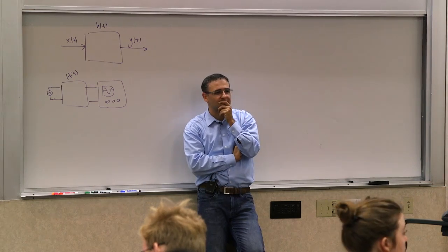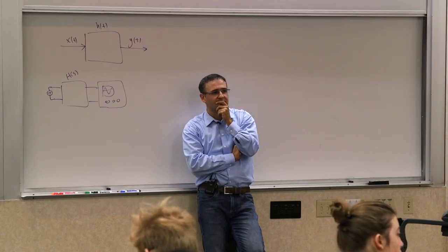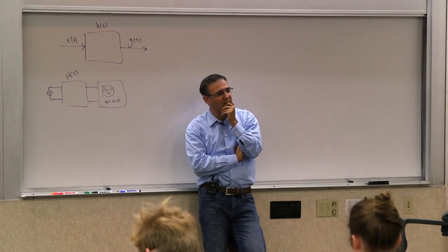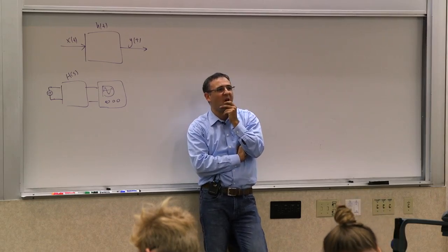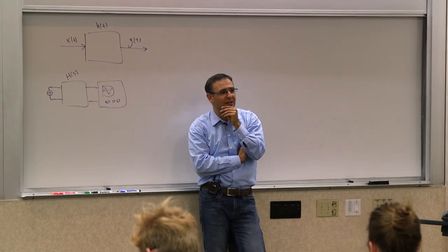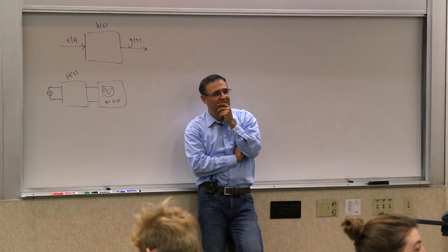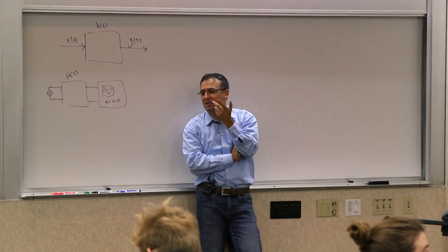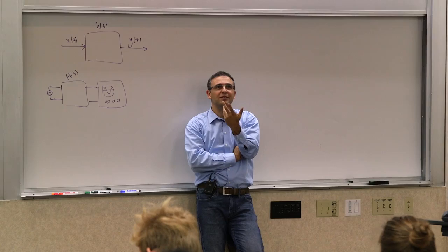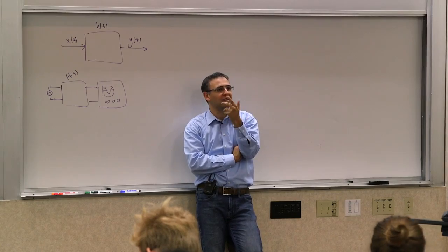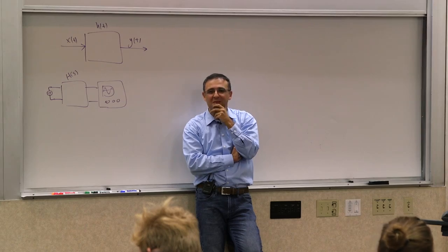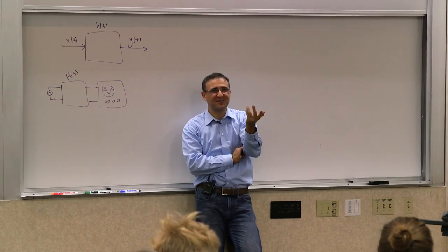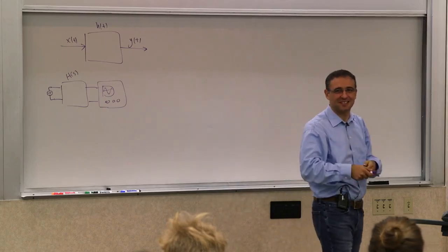Yeah. Maybe start by trying just a DC input first. Okay, so start with a DC input, and then you will probably get a DC output. Let's say I tell you this is an LTI system, so you don't have to worry about nonlinearity. Yeah. Try to give as much impulse response as you can. He says to give it an impulse. So impulses are very nice theoretical tools, right? How do you generate that impulse in the lab? Sure, you made my point. You said short the battery or something like that.